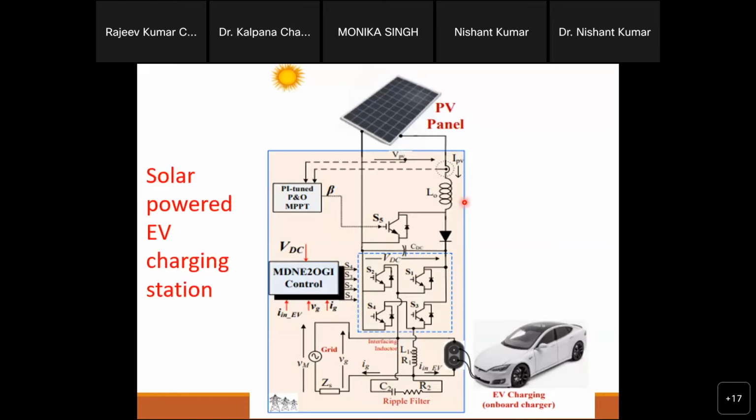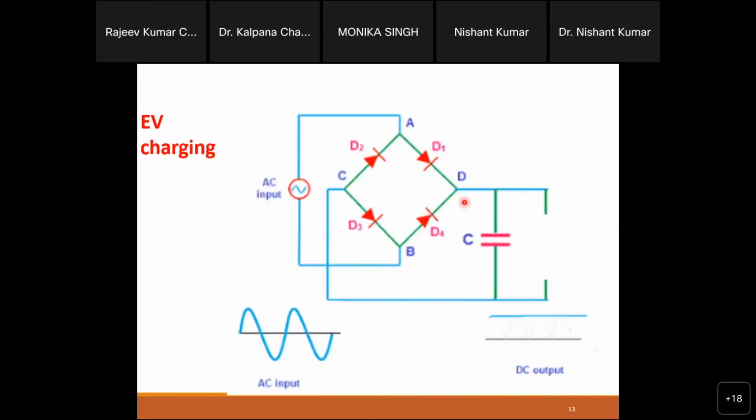If you think about standard adapters, then that is good. You take the power from the grid and convert it into DC, and then you charge the battery of the electric vehicle. This is the standard behavior. If someone uses those standard chargers, then this is good. But in the Indian market, I will say everyone is not going to use those high power adapters. The majority of people, I will say, will go with an additional charger, and those chargers will be based on diode rectifiers.